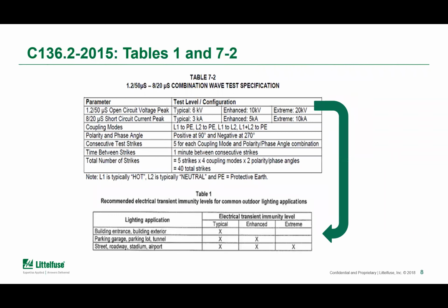So a little bit more detail on C136. C136 has a couple of different test requirements: a test requirement for a ring wave, a test requirement for electrically fast transients, and then of course, electrical tests for lightning. I'm going to focus on the lightning because, as I mentioned before, if you comply with the lightning requirement of this standard, more than likely you'll be able to comply with the other two, ring wave and EFT, which are geared more towards line switching or load switching on the grid, whereas this is geared more towards lightning strikes. If you comply with this, you'll typically be able to meet the other aspects of the C136 standard.